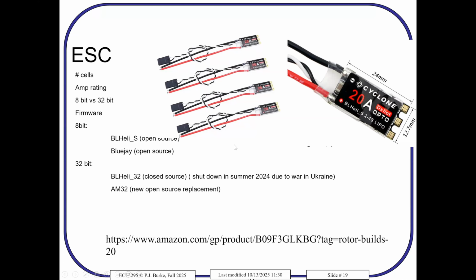The number of bits is either 8 bits or 32 bits. Almost everything these days in microcontrollers is 32 bits. There are very, very few 8-bit microcontrollers left, except for very low cost applications with very low performance needs. This is an application where we don't really need 32 bits. So to save you money, or the school money, I picked an 8-bit ESC instead of a 32-bit ESC, because I'm trying to keep the cost down so that everybody can have hands-on experience.